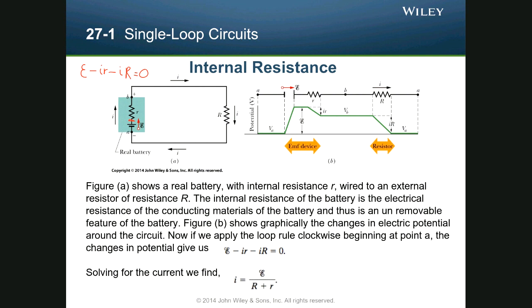The green line, no, it's not the potential energy, it's the potential difference. We've got to be careful because we're going to start calling potential difference potential. Notice that, look at the units. If it were potential energy, it would be joules. The units here are volts, so that's potential difference. So if we didn't have a resistor on the right, then this term would just be crossed out. All right.